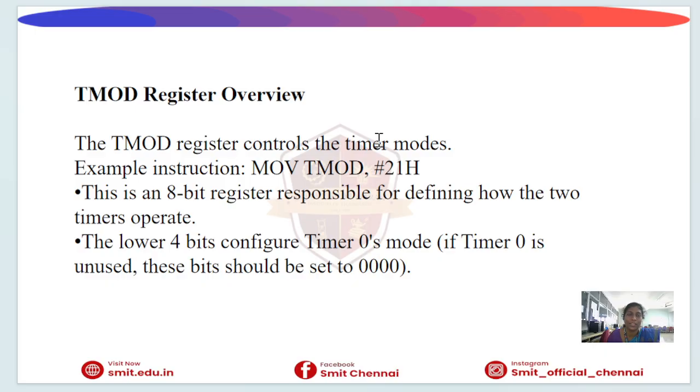It is an 8-bit register. It is used to configure the timer or counter selection, operation mode, and gate control. These are the configurations of the TMOD register.